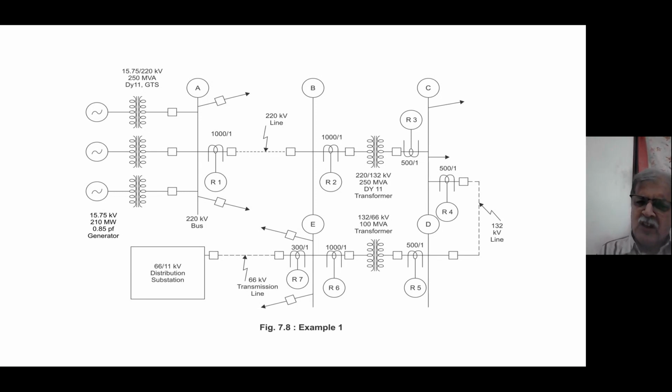Now SF6 breakers are very good. They operate within 2 cycles, but those 2 cycles you have to consider. And then you have to consider overshoot of relay R6. All these things are very less in static and numerical relays. So you can reduce the time margin between R6 and R7. That is true. And if you use numerical relays and reverse interlocking principle, then you can very nicely reduce the time margin. But right now we do not jump to that.